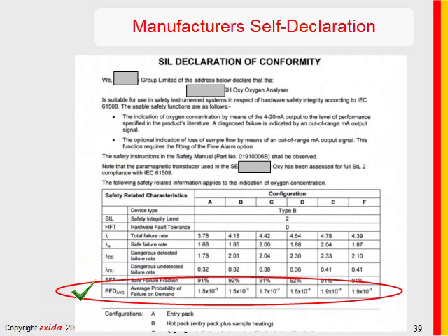One of the reasons it's not good is we had a case where an engineer picked a PFDavg value from a report and used it to design a safety function which wasn't even close to being sufficiently safe.